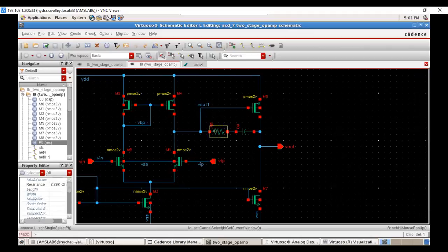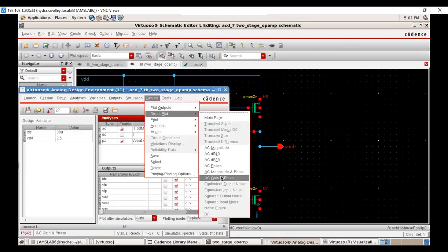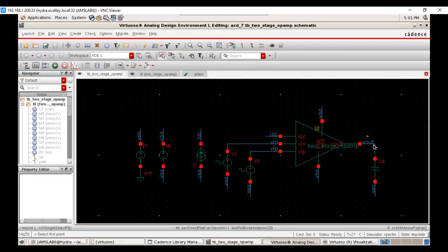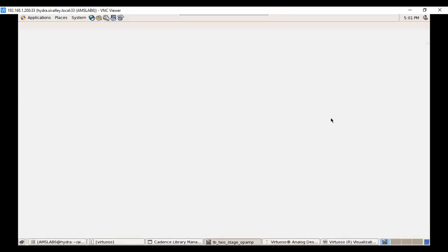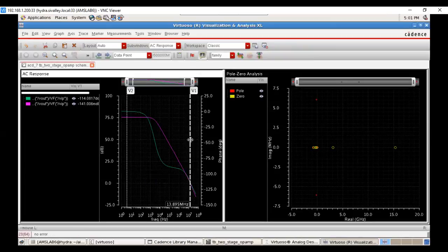Okay. So if I place that exact same resistance, I did not change even the values, I'm able to see the graph as well as the pole zero locations. You can see it here. Now this is a graph where we are having phase margin as well as the gain. You can see phase margin is coming as 114.